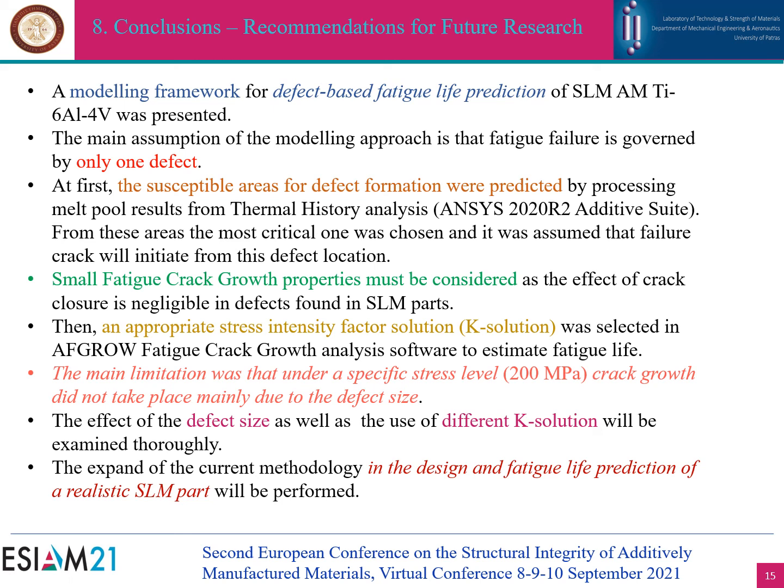Small fatigue crack growth properties must be considered as the effect of crack closure is negligible in defects found in SLM parts. Then, an appropriate stress intensity factor solution was selected in AFGROW fatigue crack growth analysis software to estimate fatigue life. The main limitation was that under a specific stress level, about 200 megapascals, crack growth did not take place, mainly due to the defect size.